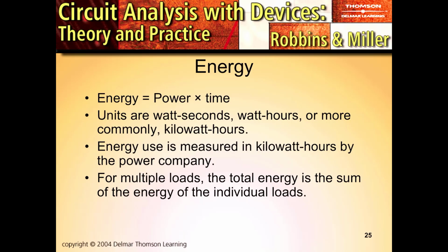So if we think of 2 individuals owning a 1,000-watt heater, does that mean they're going to be billed the same every month because they both have a 1,000-watt heater? No. It's going to be determined by how long they run that 1,000-watt heater. So we have time involved here. So units for energy are watt seconds, watt hours, and most commonly, if you were to look at your energy bill, you're going to find a unit of kilowatt hours.